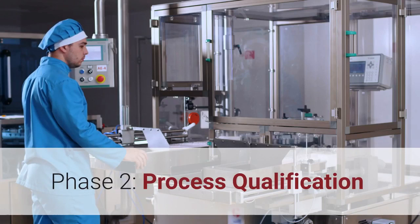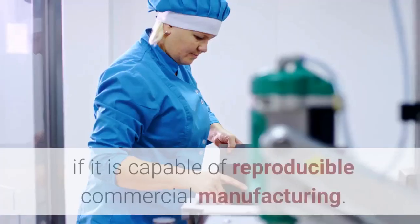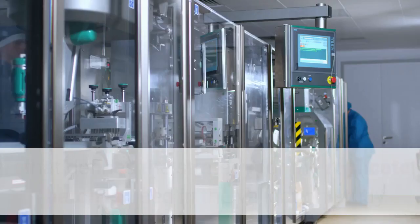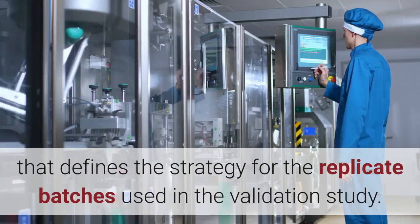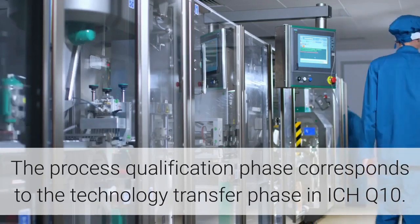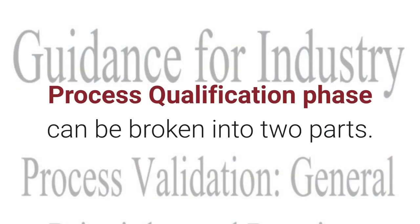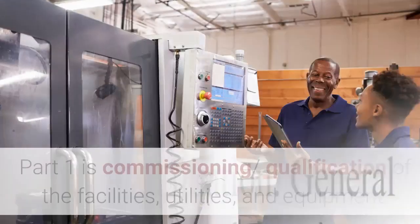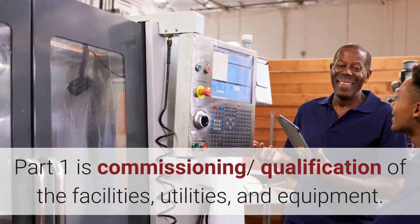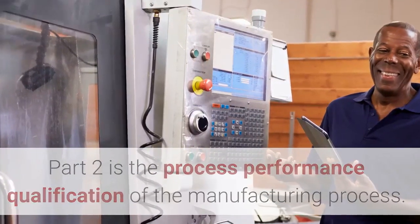Phase 2, Process Qualification. Process qualification is the evaluation of the process to determine if it is capable of reproducible commercial manufacturing. It is a point-in-time event that defines the strategy for the replicate batches used in the validation study. The process qualification phase corresponds to the technology transfer phase in ICH Q10. Process qualification phase can be broken into two parts. Part 1 is commissioning qualification of the facilities, utilities, and equipment. Part 2 is the process performance qualification of the manufacturing process.